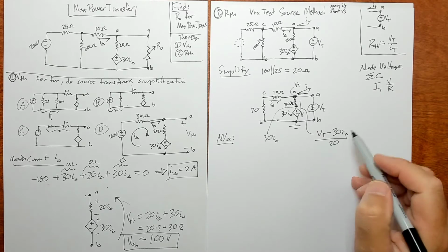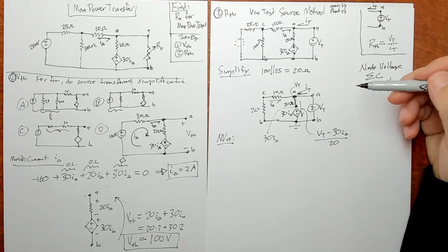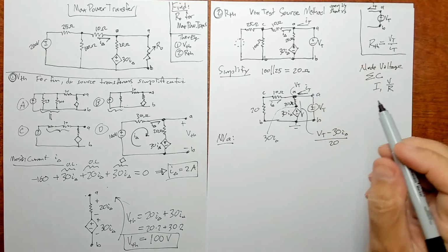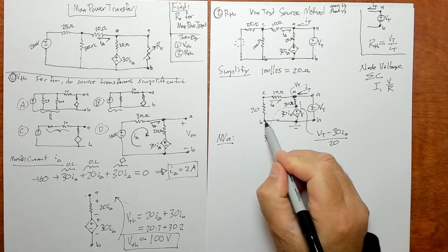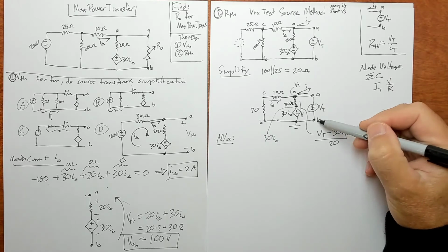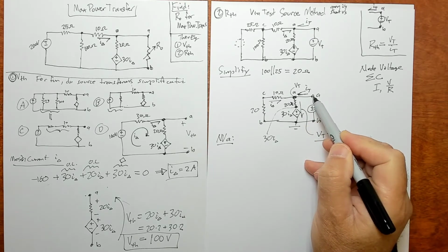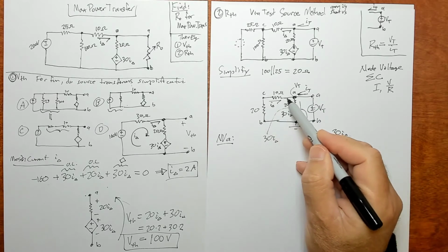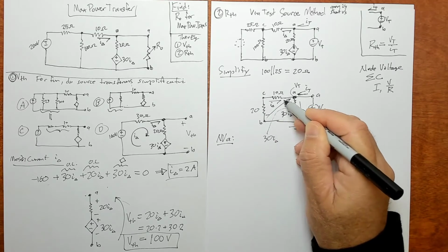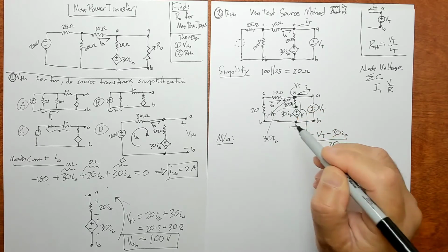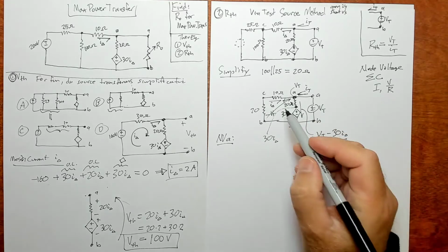In terms of VT and I delta is going to be a problem, so we need an expression for I delta. If you look, here's node A, here's node B, and V sub t is the voltage across nodes A and B. So really, it's positive at A and negative at B. So across these two resistors over here is VT. So the positive polarity would push the current in the opposite direction from what our reference is.